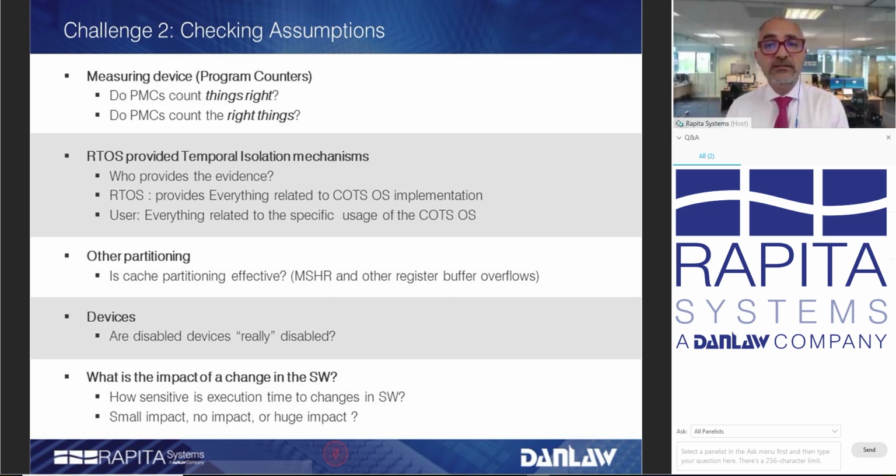In an ideal world, that would be it, except that there are side effects where at the lower level, this isolation is not fully guaranteed. Without trying to go into much detail, there's a special register called the miss status register, where there's a little buffer that holds the transactions that are in flight from the cache to the memory.